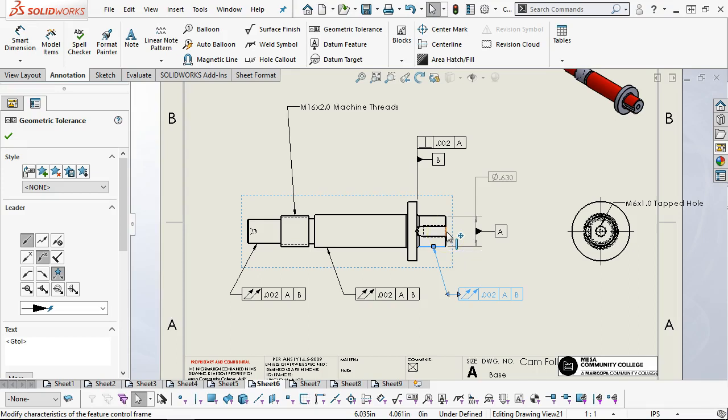The issue is that when I'm holding onto this, I'm probably going to have a large piece of stock that I'm going to be able to machine all of this geometry off of the left side. And even though I'm really focused, I want to control this end dimension, because that's what that big honking chunk of cam is rotating around. What's taking all of the load. It's not really my best datum.